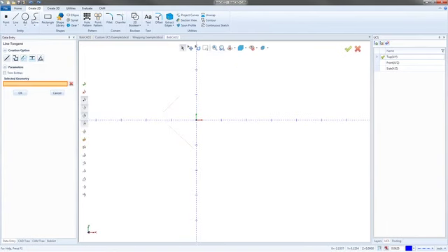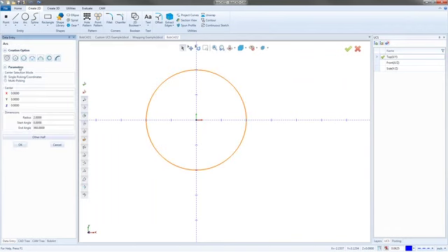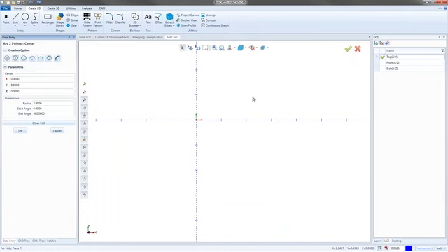So I'm going to open up, let me get rid of the lines on this junk here and go back in. Now we got a blank window. So the rest of these functions are primarily, and I won't say fully, but primarily they're going to be used for sketching. So arc 2 points lets me define an arc based on the radius. So I'm defining where the center point is. And then from there, I'm dragging the radius until I get whatever size I want. So just like that.